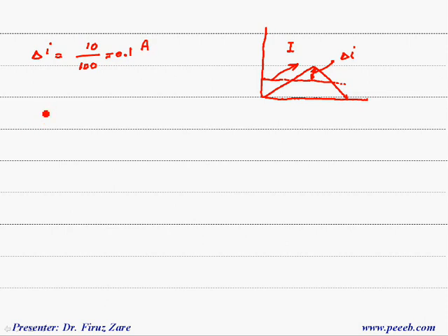So when the load current is maximum, which is basically 10 volts over 10 ohm, this is the load current for R equal 10 ohms, which is 1 amp. So here we can see that the ripple is less than the load current. That means for this condition the system operates in continuous conduction mode. And for the capacitance value, we can find it according to the equation, which is basically 12.5 microfarad.